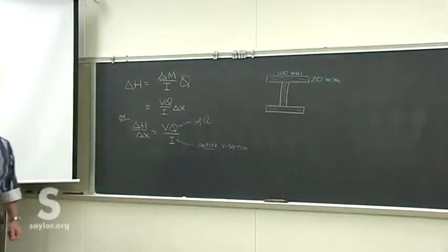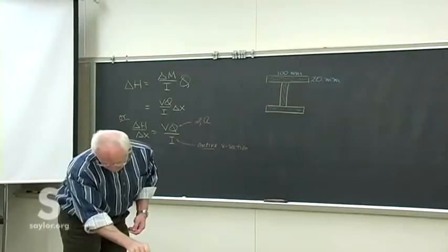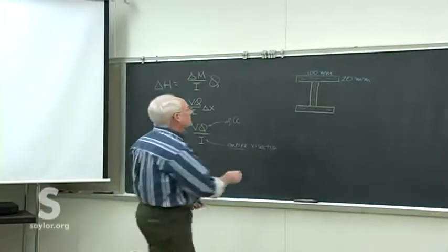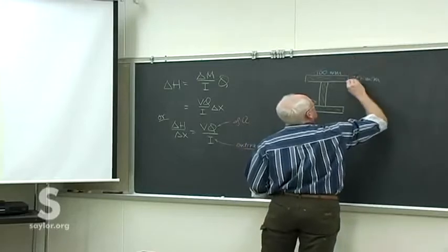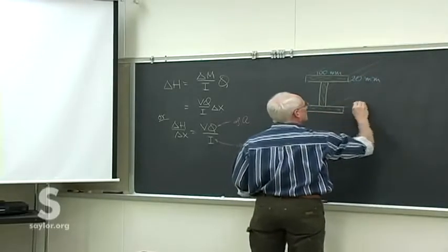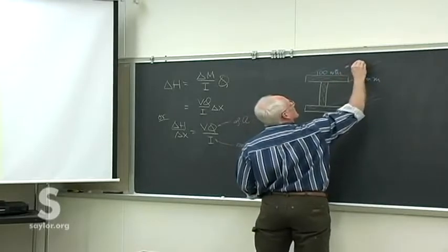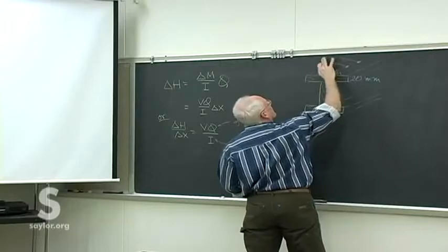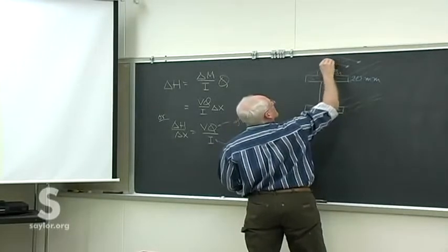All right, so there's our beam in cross section, and then we want to find the shearing force in each nail, expecting to put them at approximately 1-inch intervals. We'll put them at 25 millimeter spacing between each nail.